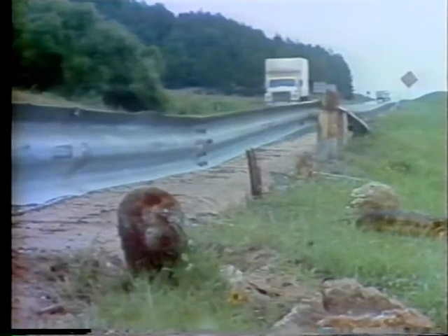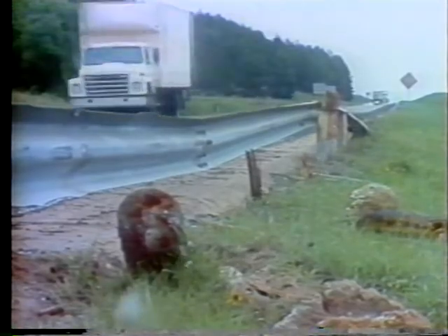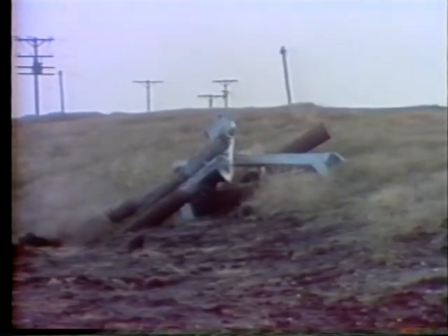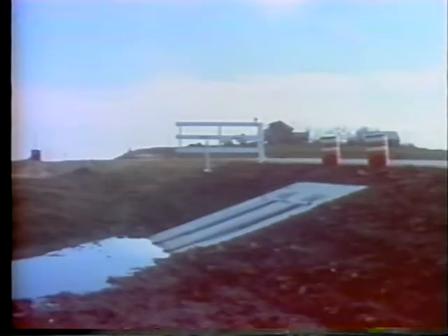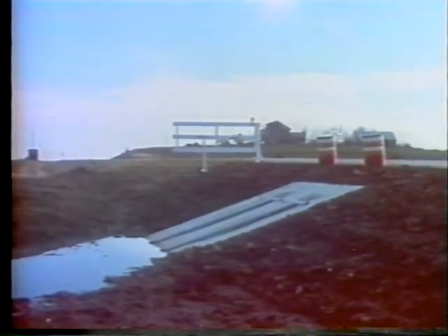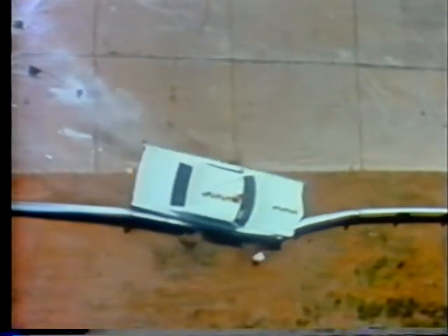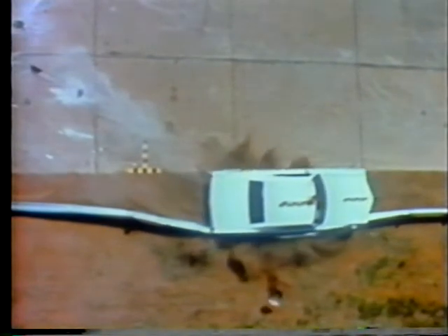When a large section of an existing roadside barrier is damaged or scheduled for replacement, slope flattening and barrier removal should be considered. It can be more dangerous for an errant vehicle to strike a roadside barrier than it would be for it to run down a flat side slope and onto an established clear zone.